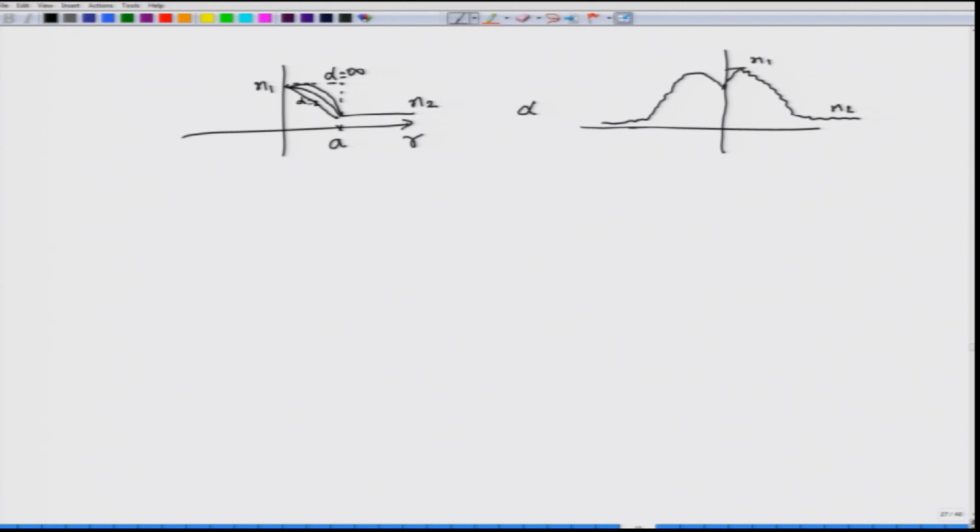Of course, this dip is unavoidable, as I told you, because of the manufacturing problem, and also notice that the refractive index is not going like a smooth curve, but rather has jagged edges. That is because the refractive index profile, despite whatever manufacturing improvements we have made, is not really giving you a smooth profile. Okay. Those surface roughness, if you were to examine them, would give you a jagged refractive index profile.